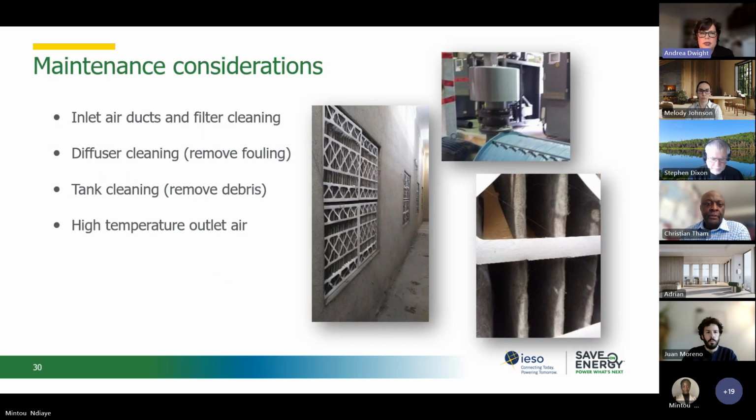One maintenance consideration is really making sure that everything's clean. If you have a turbo blower, you probably are already dealing with this because the inlet air ducts have to be kept clean. But with other systems, centrifugal blowers, multi-stage ones, they can chug and chug, and you don't realize because the system's running that you're actually losing money. So make sure your airflow filters for your inlet air are kept clean, so the pressure drop isn't increased. And of course, the loads on your motor would increase.